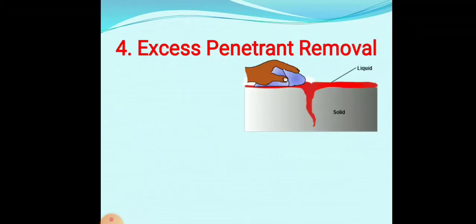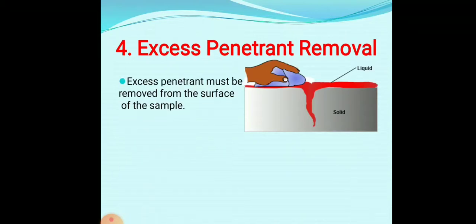Fourth step is excess penetrant removal. After the penetrant is applied, some time is given for it to flow into the cracks. After that, the excess penetrant can be removed. The excess penetrant must be removed from the surface of the sample.